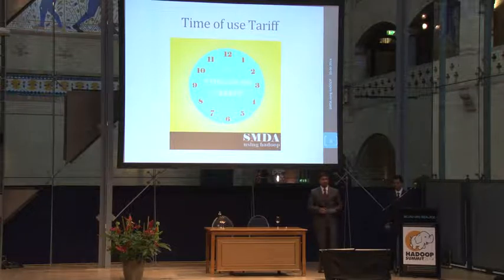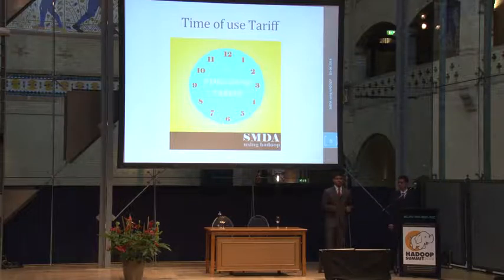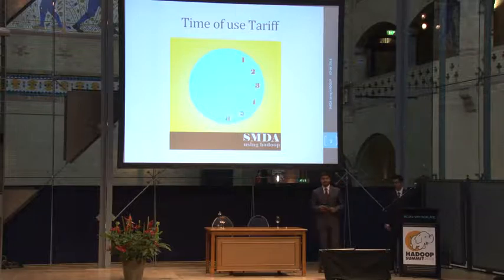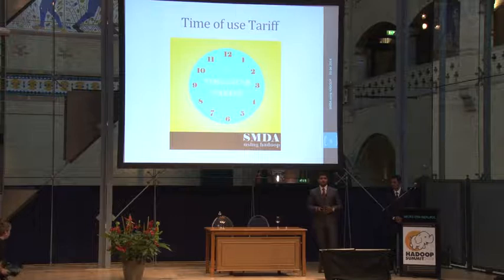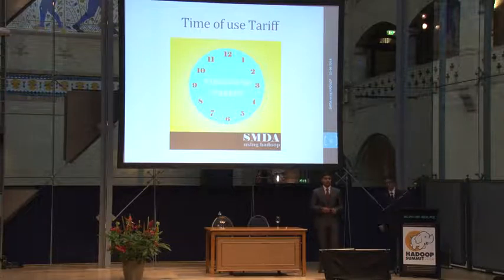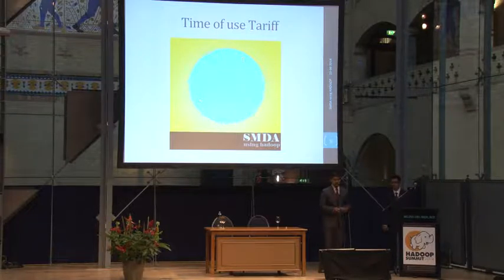From a customer point of view, if a customer is doing his own analysis, or is provided with information that at certain hours, a couple of hours, there are peak loads, we can manipulate him to shift his time from that peak load to some non-peak load. He can use his normal appliances, like the washing machine, in a later part of the day instead of using them at peak times. So basically, this is time of use tariff.